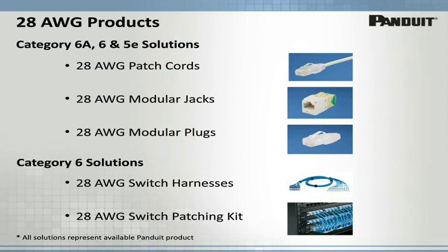No, Patrick, in that one, no more so than it would be with any other gauge of cord. And actually, that's a good opportunity to point out that while we have focused in this presentation almost exclusively on unshielded twisted pair examples, all of the dimensions that I mentioned and examples I was showing were unshielded twisted pair. That's because of the prevalence of that in the U.S. market. In the case of the Cat6A 28 gauge cords, we actually do offer both a shielded and an unshielded UTP solution. So many times for EMI concerns, low frequency noise and such, customers will look to shielded solutions, and for those situations, we do have the 6A 28 gauge cable. But as a simple response, there are no more concerns than you would have otherwise for other types of common cabling.